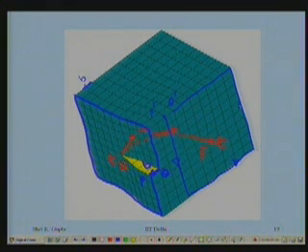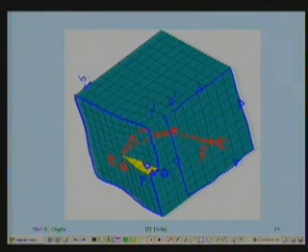You can count your steps. So Burgers vector is this. This is the Burgers vector. This Burgers vector and this Burgers vector. Check that. Direction and magnitude. Same. So Burgers vector of a dislocation line is invariant. Similarly, if you find the Burgers vector at this point, it will be the same.